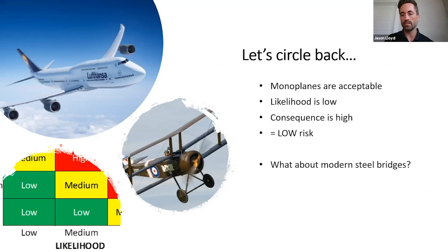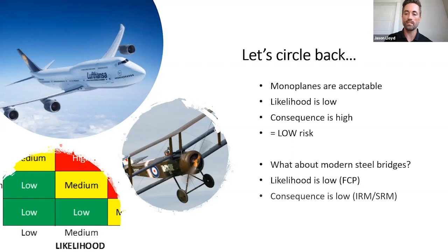So what about steel bridges? As we've talked about today, likelihood is very low, particularly for bridges fabricated to the fracture control plan. And if we have internal member redundancy or system redundancy, the consequence is also low, which gives us a low risk as well.